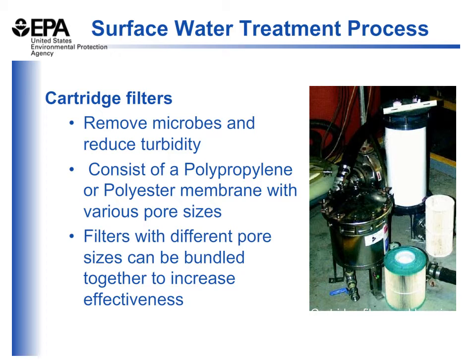These filters need to be removed and exchanged on a regular basis, and the size of the pore spaces that the filter has will depend on the type of material that you're needing to remove. If it's removing larger suspended particles, the pore size can be bigger. If it's removing smaller suspended solids, it will need to be a smaller pore size filter. And often if there's a variety of different sizes of sediments or particles that need to be removed, the filters are used in series, with the larger filter size first, followed by the smaller one, in order to remove the larger particles and prevent them from clogging the smaller pore-sized filter.